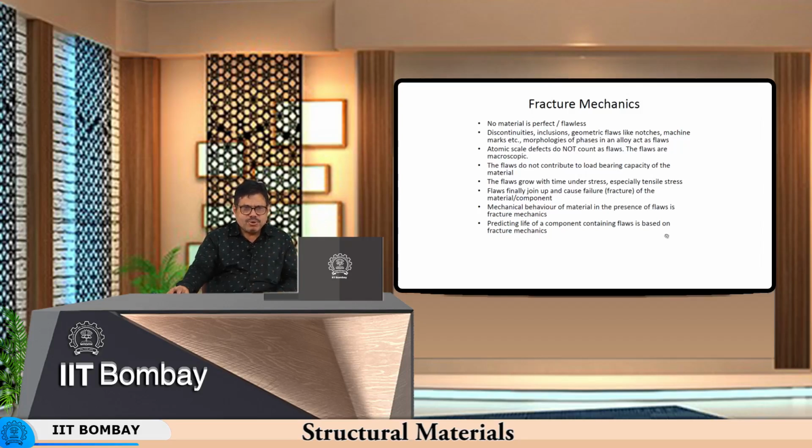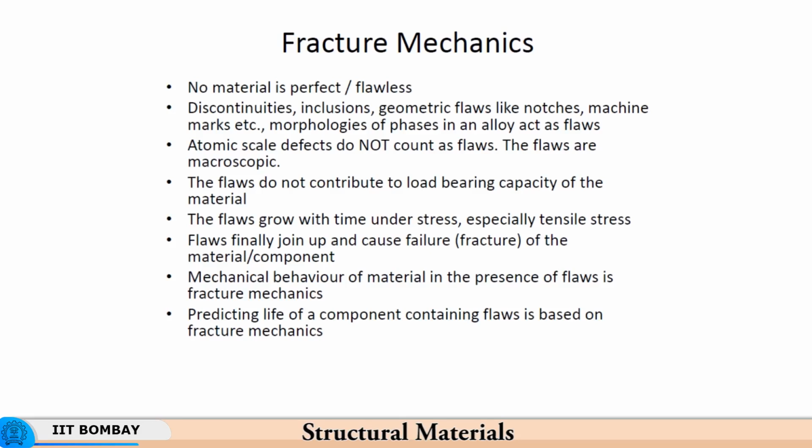So, the flaws grow in time under stress, and especially the tensile stress, because in compressive stress the flaws do not grow and the interface between flaws and the material gets kind of compressed together. So, there is no room for any breaking up, or there is no room for any delamination of interfaces. But if you have any delamination, it does require a tensile stress to be acting on it. So, naturally you will find that flaws grow with time under stress, especially the tensile stress.